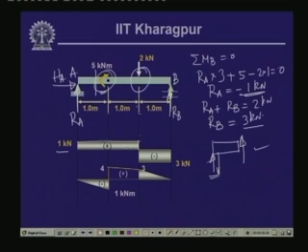Now, at the load point there is a changeover from plus 1 to minus 3. So, this is the 3 kilonewton load which is acting on our shear, and then finally again it is constant over this particular region. So, this is the diagram, the shear force diagram.